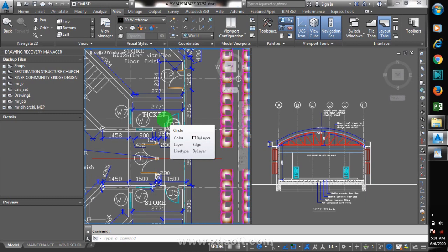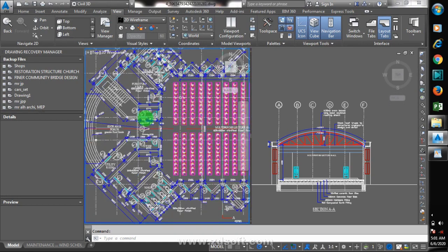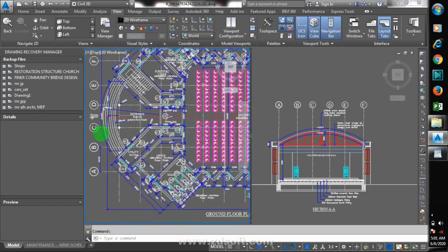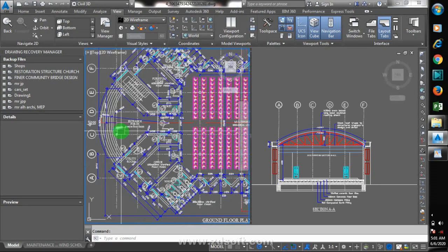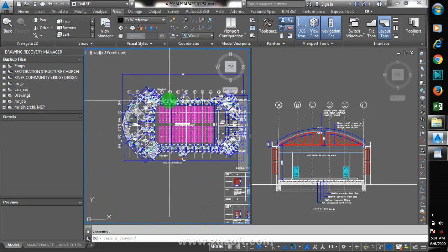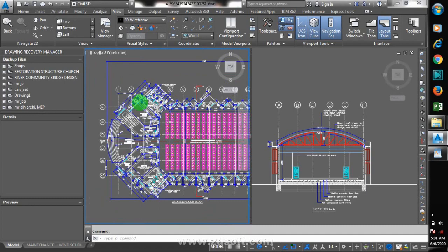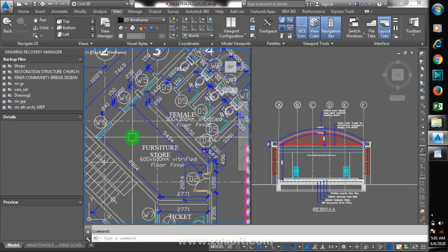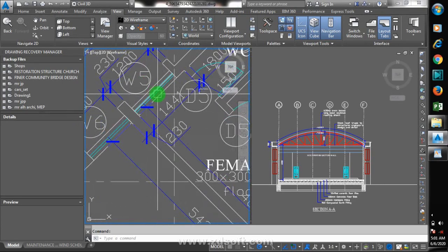First thing you do is to take off all the windows, delete all the doors, delete the windows, delete all architectural annotations and dimensions. Okay. Now to do that, if your building is actually in layers, it's very easy. Okay, if the design is actually in layers, it's very easy to achieve that.